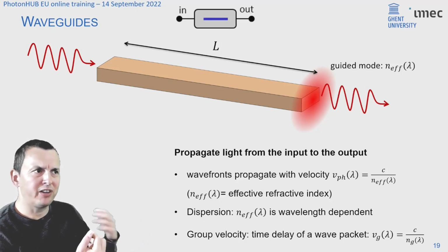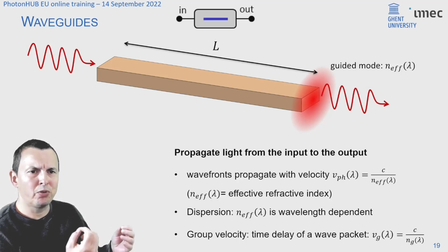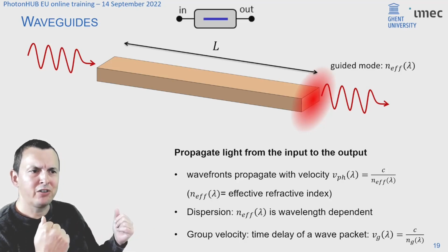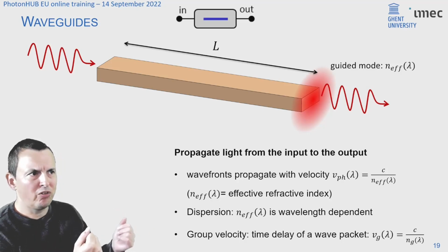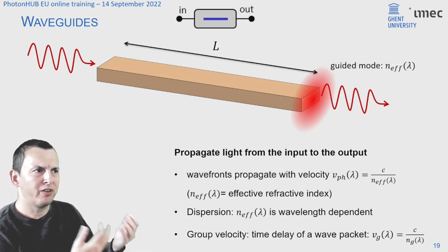So there's a certain time delay and a certain phase delay of that wave as it propagates along the waveguide. So the transmission, in contrast with what people do in electronics, you cannot just assume that if 2 points are connected with a waveguide, the connection is instantaneous. So you need to describe the signals propagating through a waveguide with a certain velocity.